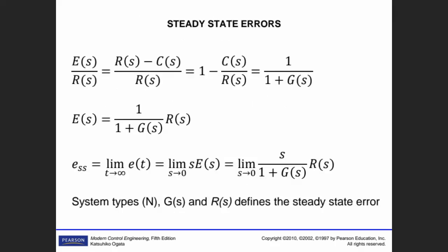Now we remember the steady state error. You remember that error is between the, let me say right away, R(s), your wish. C(s) is the reality. The difference between those is E(s). Okay. R(s) minus C(s) over R(s), percentage value of error, which is equal to 1 minus C(s) over R(s).